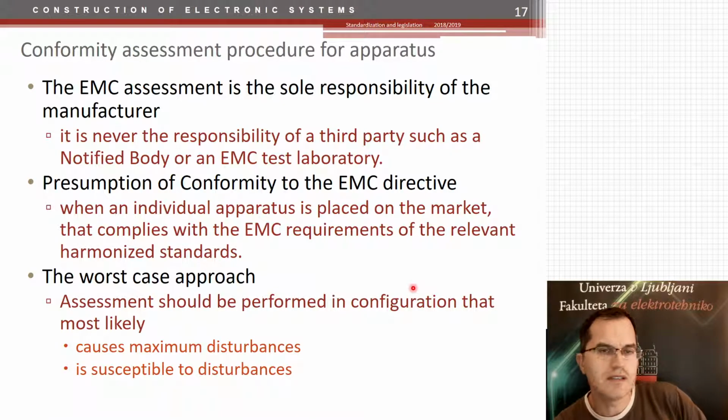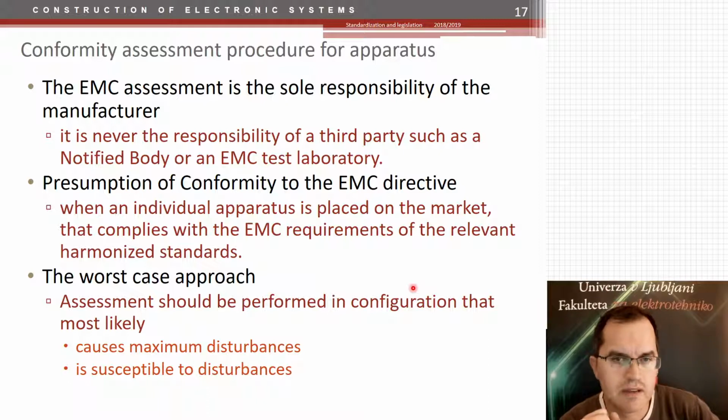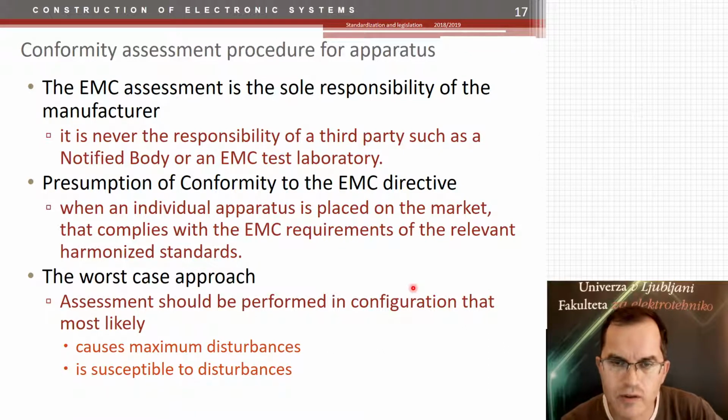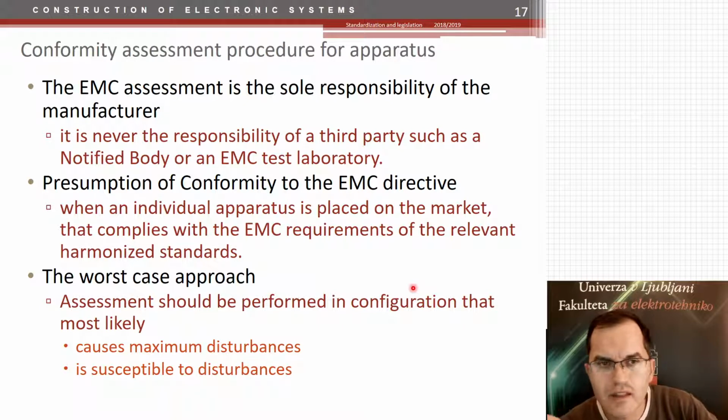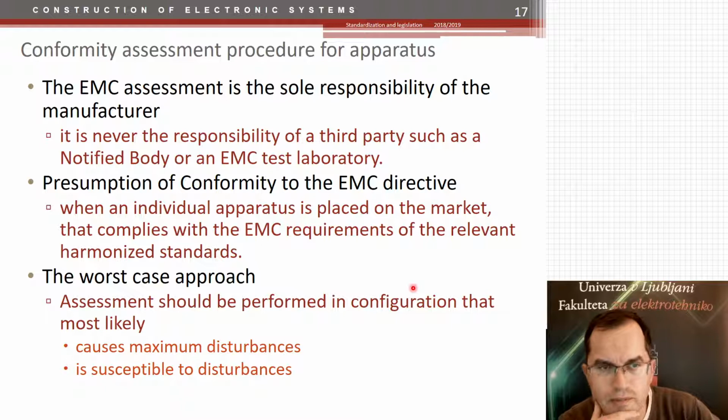So the EMC assessment, whether the device is compliant with the EMC, the apparatus I'm talking about now, is the sole responsibility of the manufacturer. Even though you go to the SIQ and they measure the radiation for you, it's still not their responsibility for the rest of the 100,000 apparatus you will be producing in the next year.